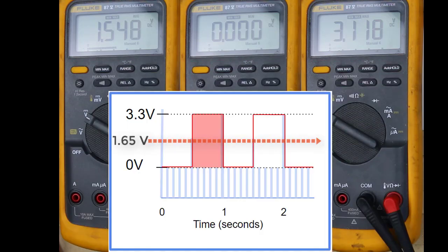On a previous video, we discussed that a pulse width modulated digital signal with a 1 Hertz frequency and a 50% duty cycle would essentially divide the high voltage in half. And we see this exact behavior in our multimeters as we measured it. We went from 3.118 and divided that by half, and we got the value 1.548. Because the frequency is so low, we can actually measure this on a multimeter. As we increase the frequency, it becomes more challenging to measure both the minimum and the maximum, and we will demonstrate that in future videos. Next, we're going to do the same script, but we're going to measure it with an oscilloscope.